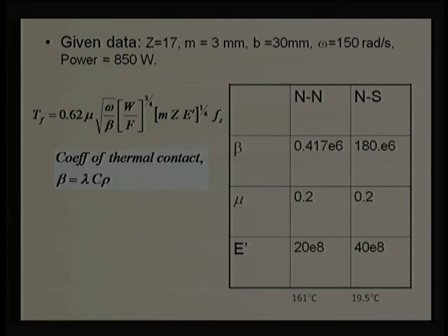So, we will continue our gear topic in our next lecture. In the next lecture, we will be considering what kind of failure analysis we can do, or what are the possibilities of gear failure. We have explored one possibility in this case, particularly scuffing failure, which happens at high temperature, with lack of lubricant, or a very high coefficient of friction and lesser thermal conductivity. But there are other possibilities of failure of gear we will be exploring in our next lecture.